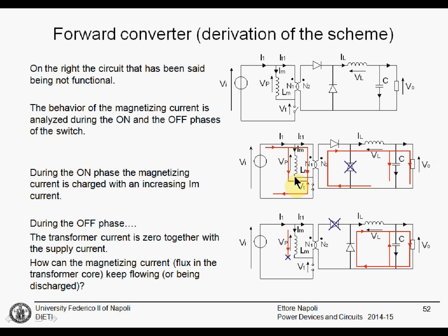The current that goes through the magnetizing inductance is just lost current. It's not a big problem for efficiency, because there is an inductance, so there is some stored energy that you can reuse. But in order to have maximum efficiency, this inductance should be infinite in order to avoid this current flow.